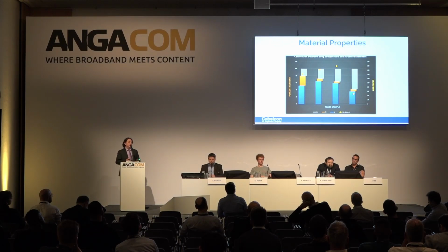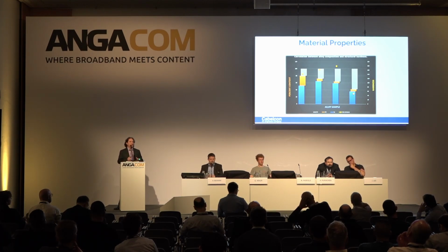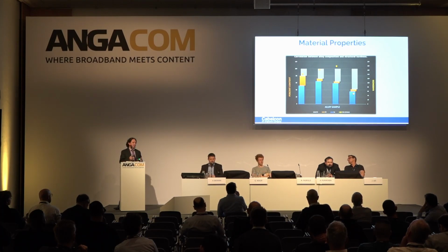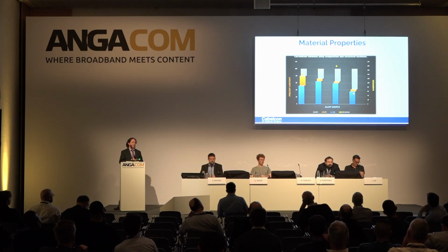And again, we're talking about material properties. A zinc, copper, nickel alloy, nickel brass connector. There's, again, a wide range. I'm not going to delve very deep into the metallurgy, but as you increase the composition of zinc inside the alloy, you can affect the hardness. In the first three, we can see that the hardness is increasing with the yellow dot as the zinc level is increased. As the zinc in the alloy is increased, you can actually oversaturate the alloy with zinc and it suddenly becomes very soft. So it's not only the metallurgy, but also the definition of the mechanics which can affect how well the port will function in the field.